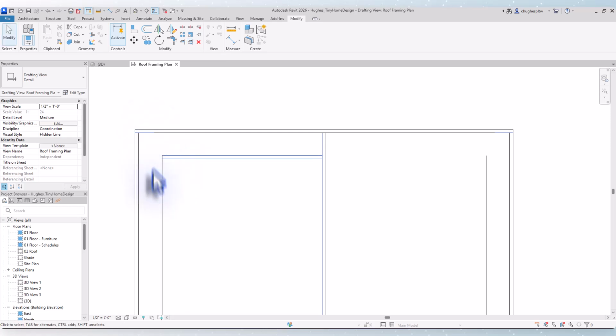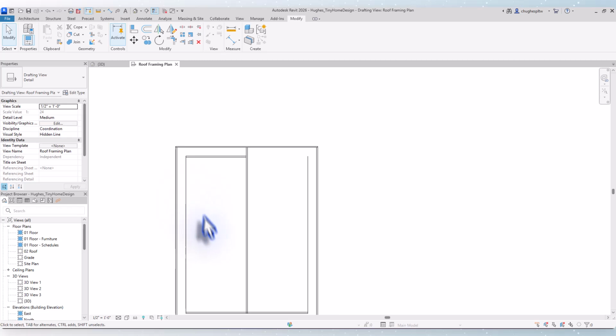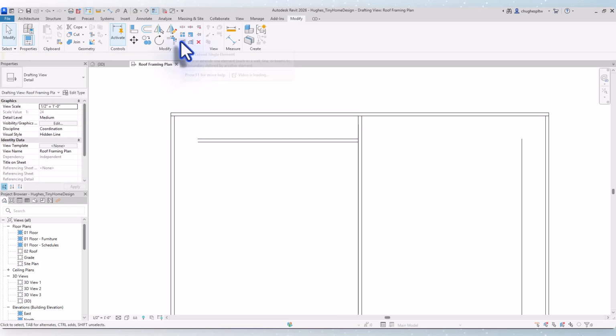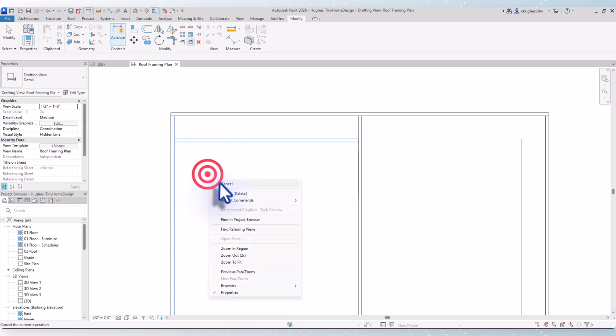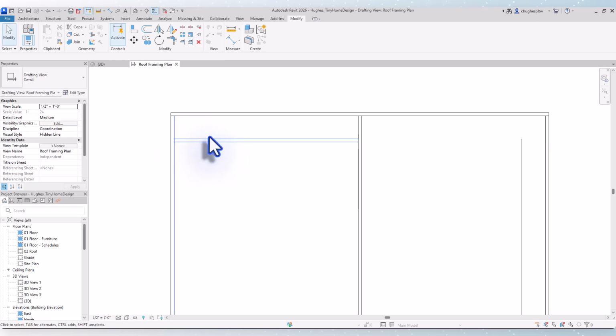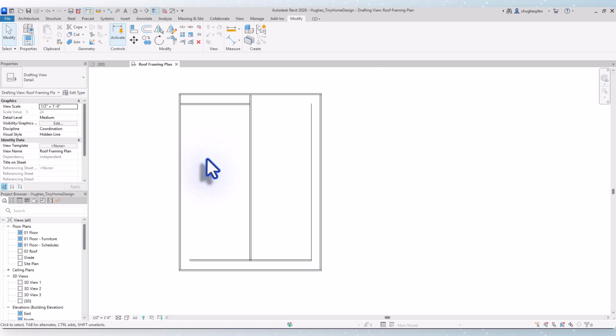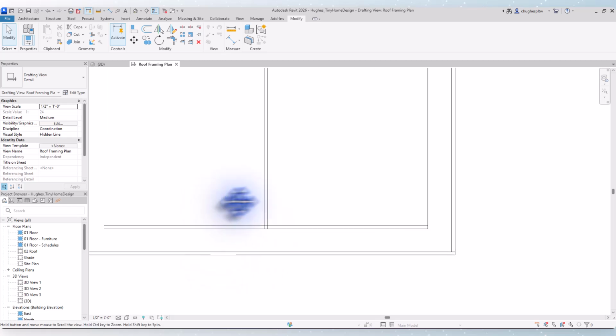The other thing we can do is get rid of this left side line. And I'm going to trim and extend to this line, these 2. That way that'll show you where the rafters will connect. So here's the ridge board, here's the rafter where it connects, and then here's going to be the end board that we'll use to connect to as well. So a little bit of our trim board there to help cover those things up. All right, so then same kind of situation down here on the bottom.